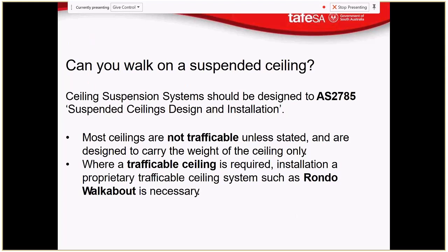Ceiling suspension systems should be designed to Australian Standard 2785, Suspended ceiling design and installation. Most ceilings are not trafficable unless stated and are designed to carry the weight of the ceiling only. So not really what you see in the movies, people passing through.